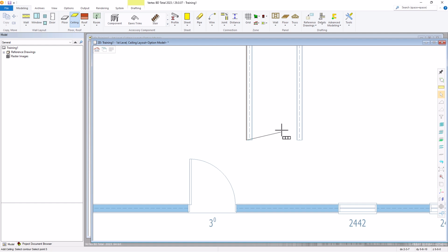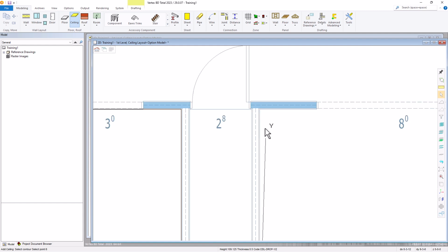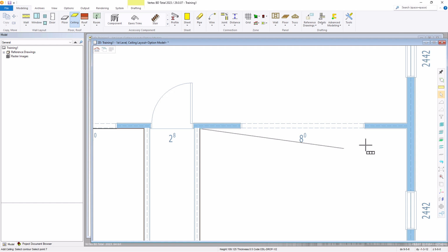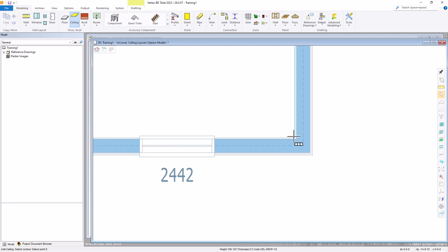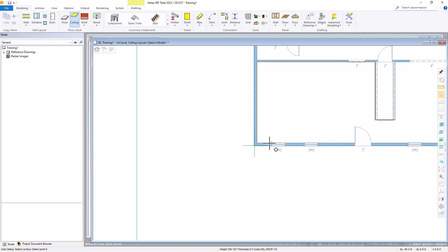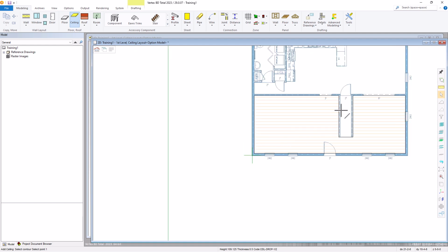We are going to have another stairwell here. We're just going to come across and ignore this area. Back across to this corner. I key to lock into vertical. And U key in horizontal and back to where we started. V to confirm. So that's one area.